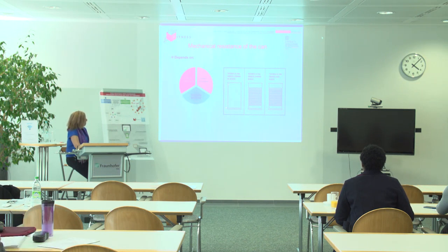Here I have no beading. I have a thickness of 0.26 and the hardness is standard. Okay, I can reduce the thickness from 26 to 21, still keeping the hardness of the steel, but I need to use beading.